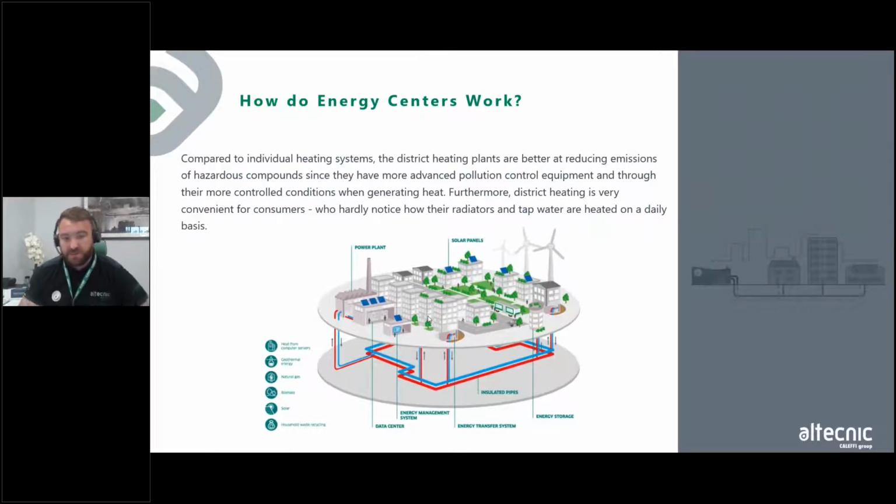And you can see there as well on this one, we've got a data center. Data centers, by their very nature, where they operate using all the machinery, generate a lot of heat. And so what this one is showing is that heat is taken from the data center, converted via the power plant, by heating this, and then used as a heat network. So we're taking what would before be a waste energy, which is the heat side of things, and we're going to start to use that as a benefit, as opposed to a negative, and pump up into the skies. So it's important to remember as well that a heat network is sized correctly.